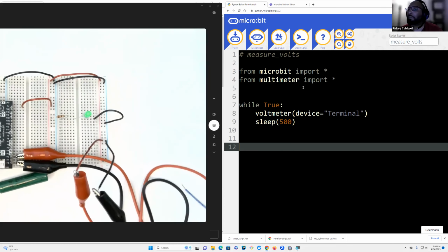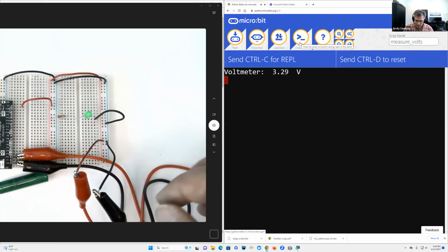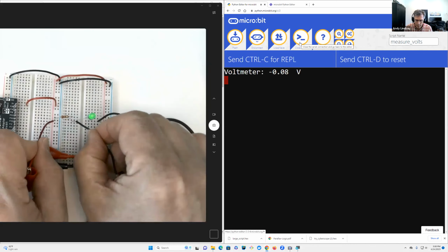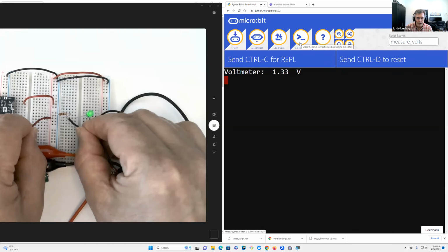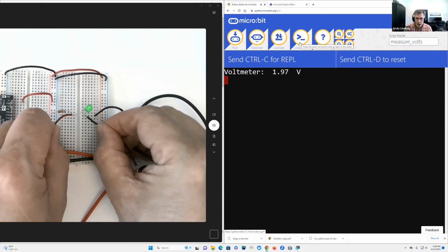We can see it. Okay, so now if you go back to your voltmeter, you can probe across the whole thing, from the red stripe on the left to the blue stripe on the right, and we'll see that it's applying 3.3 volts. Then you can probe the resistor and see that it's dropping about 1.3 volts, and then probe the light and see that it's dropping about 2 volts.